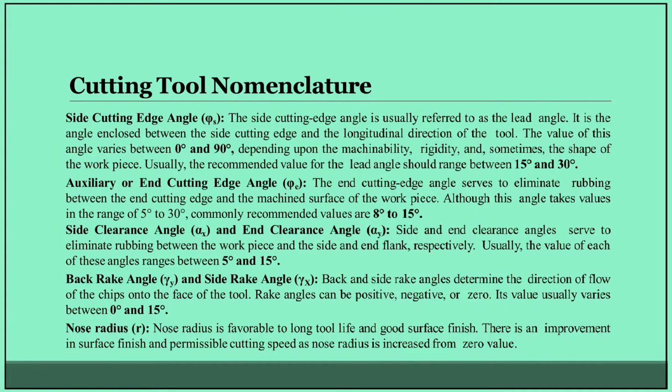Cutting tool nomenclature. Side clearance angle, alpha x, and end clearance angle, alpha y. Side clearance angle and end clearance angles serve to eliminate rubbing between the workpiece and the side and end flank, respectively. Usually, the value of each of these angles ranges between 5 degree and 15 degree.